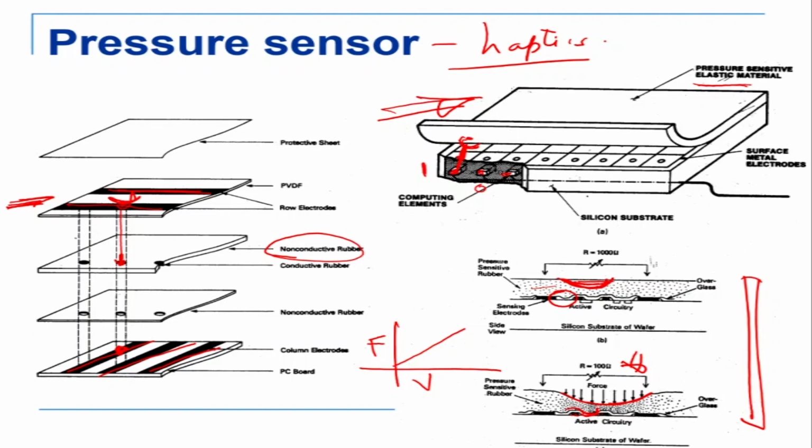Okay, so these are touch sensors, pressure sensors, which are used in robot fingertips for touching, understanding whether touch has been made or how much pressure is being applied. They can also be applied on the sole of the foot of bipeds. So for biped robots, we can apply the pressure sensors at the foot of the biped, to understand when contact has been made, what is the center of pressure, what is the zero moment point when the robot is walking, and to maintain balance.